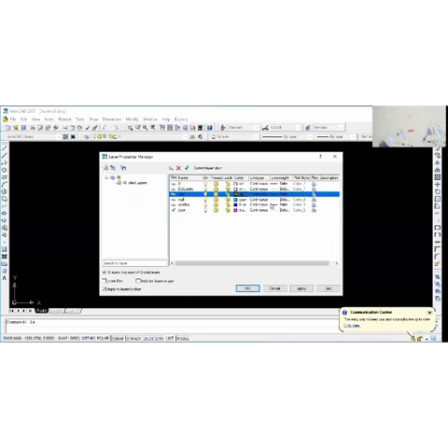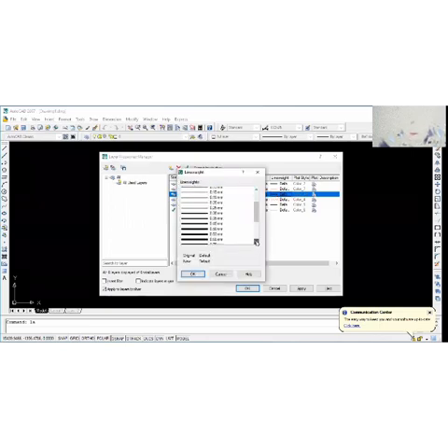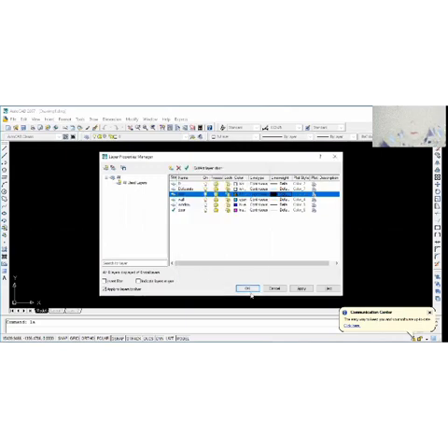So now the roof, we can also decide to change the thickness of the line of the roof. So we come here, let's take a thickness of 1 millimeter, and then okay. That is it. So now, after we are through with altering the properties of these layers, you can come here, apply, and then okay.